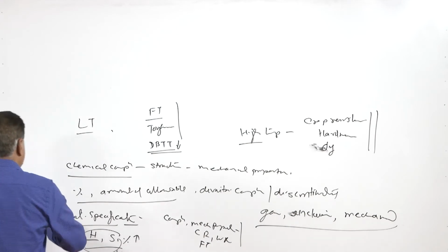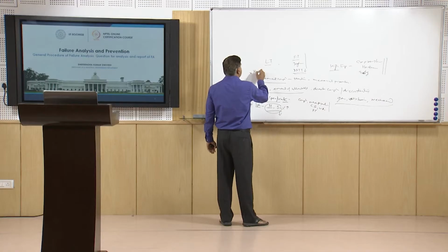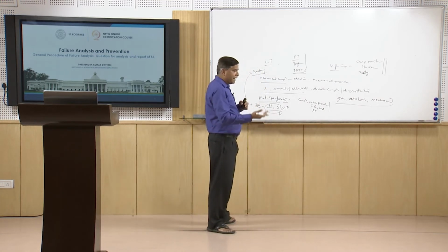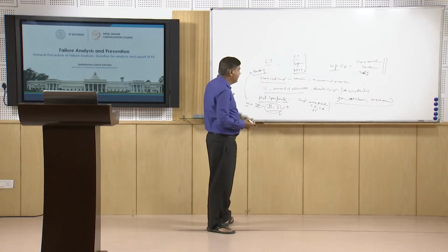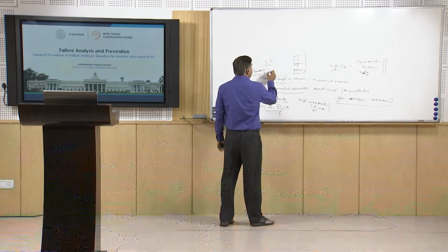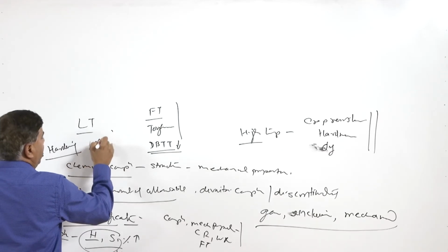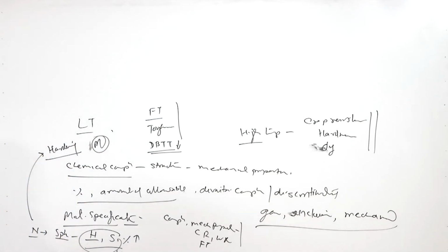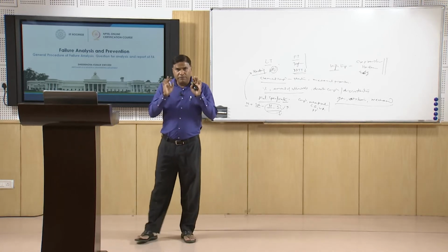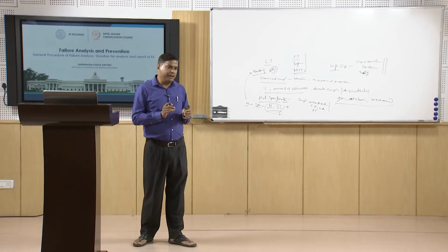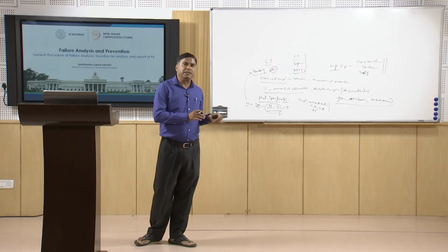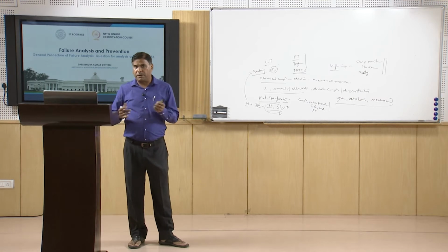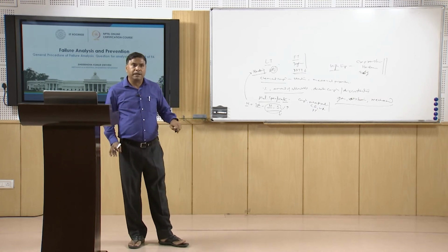Similarly, if normalizing was carried out by cooling in air, but due to the higher alloying elements in the steel it has been air hardened, that will lead to martensitic transformation, which can make the steel brittle. Therefore, we have to identify if the component has been heat treated in the manufacturing stage, and whether that heat treatment was proper or not. So, that possibility is also identified.